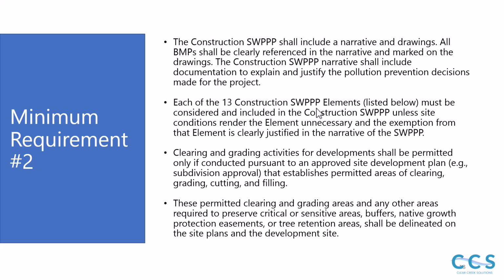The construction plan shall include a narrative and drawings. All BMPs should be clearly referenced in the narrative and marked, and the construction plan narrative shall include documentation to explain and justify the pollution prevention decisions. Each of the 13 elements, which are going to be listed and covered here, must be considered and included in the construction plan unless site conditions render the element unnecessary and the exemption is clearly justified.